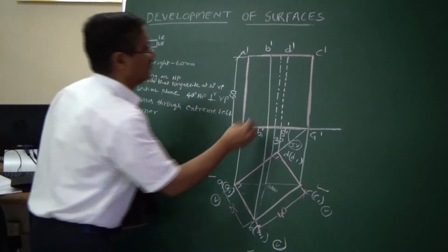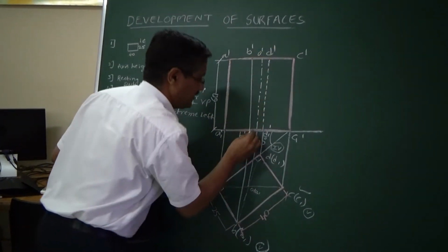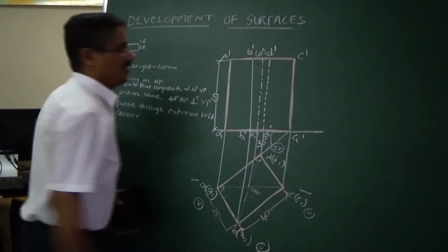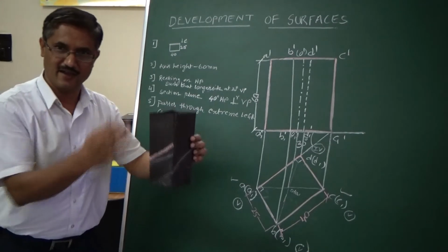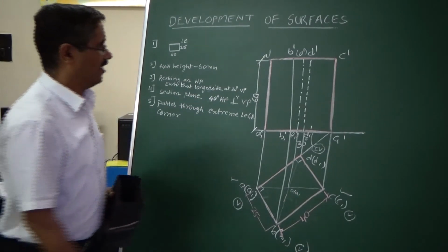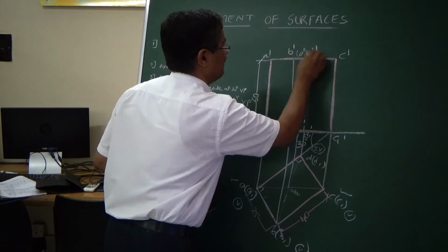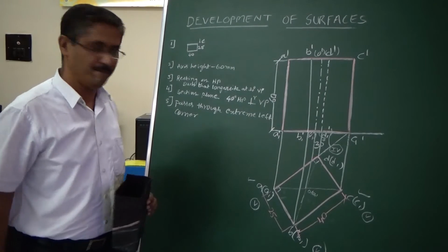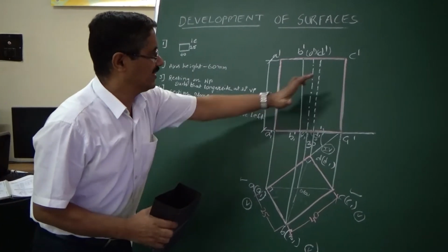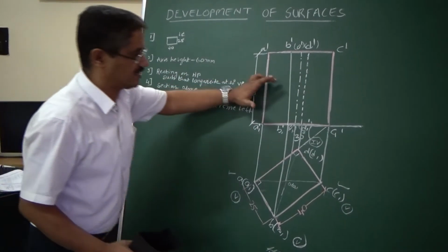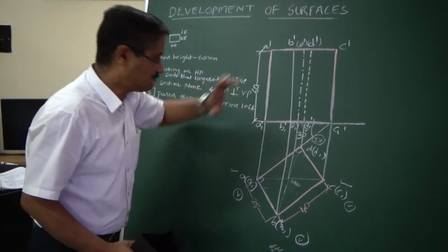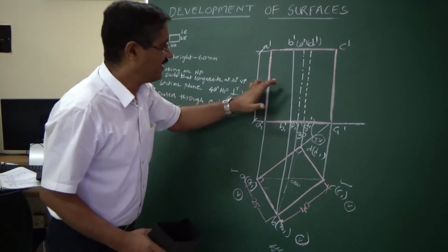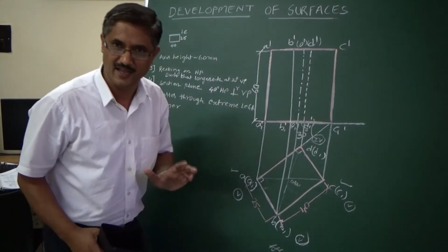Now you have to name this also. Call this O dash and this O1 dash, which is normally not visible when you look from the front, so you put it in the bracket. Also here DD1 is not visible, so you can put that in the bracket. Invisible things you will be marking with a bracket. After doing this, we have constructed stage 1 of the problem, as per the given condition, with the top view and the front view giving its boundary conditions and visibility clearly.